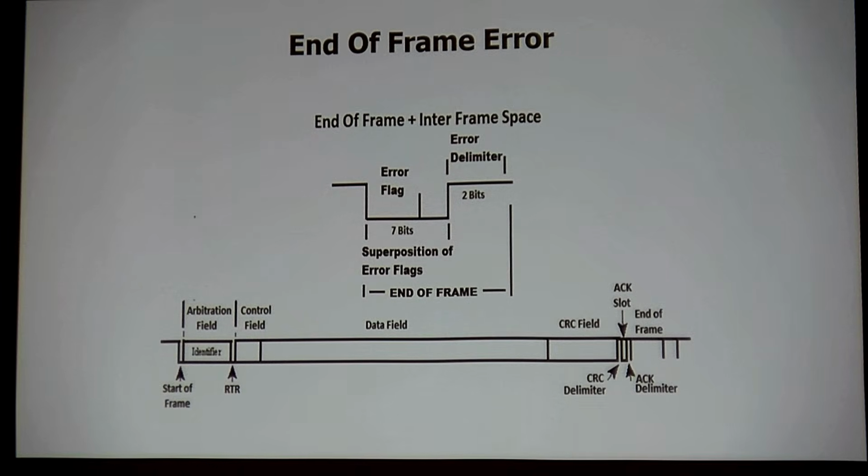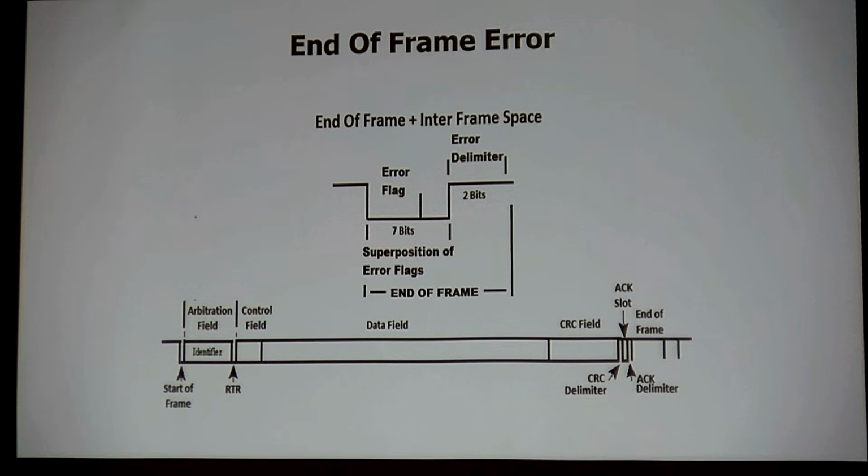Do you start to follow this? Now, I'm starting to get all these counts until I get coded, but it isn't me. It's one of the other guys whose clock is broken. That's what happens here. And this is a really common problem, clocking issues, because you're dealing with microseconds for these edges. And you're dealing with a bunch of different wiring of different lengths and temperatures. And you can get different kinds of ringing, and you can have all kinds of problems that can give you bit transmission errors. And I can keep destroying other people's messages. This guy, oh, well, I destroy him. He's bad. And then I destroy him.